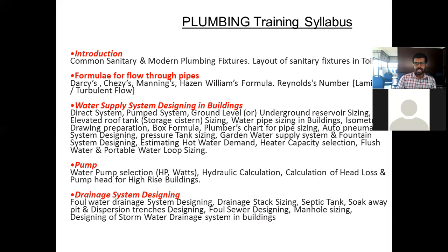Then coming to estimation of hot water demand. This mainly depends upon how much hot water we need, and with respect to that hot water, we can calculate the solar water heater capacity. Or if you are trying to use individual users, we can give what capacity you need, 10 liter, 20 liter, like that. Okay. Then heater capacity selection. Okay. And the flush water and potable water loop sizing.